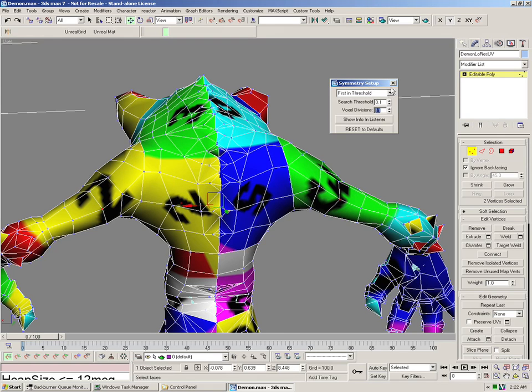number of voxel divisions, things that lie directly across the plane, sometimes from front to back. So if you've got a sphere that's got 8 segments, that segment right in the center, if you try and select those vertices, it won't, because those vertices actually lie right in the voxel plane, so it's not in one voxel or the other. So you can just kind of experiment with that. We set it to 11, and that seems to be a good number.